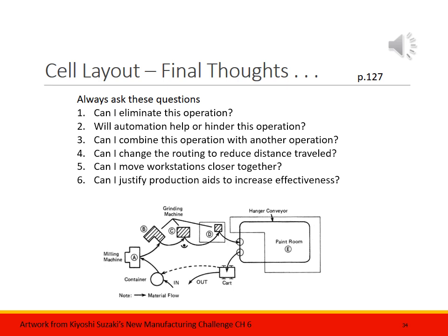Something that, maybe instead of bending over and wrenching on something, you've got a table that comes up and lifts it up so it's at the operator's eye level. And so you're going to spend some money on this lift device. And obviously, you don't want it to be a dangerous lift device when it drops and somebody's foot is in the way. You've got to think about that. But does having the process operation at table level improve things? It will improve throughput. Absolutely. It'll also help operator morale.